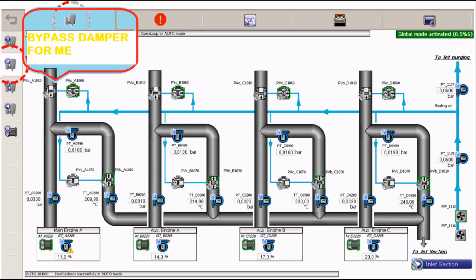The bypass damper goes to the open position if the scrubber stop button is pressed, or the emergency stop button is pushed, or the pneumatic or electrical supply to the bypass damper fails, or there is an alarm in the exhaust inlet module, or an alarm in another module or device that stops the whole scrubber. The damper control can be manually overridden with a hand wheel located on a crankcase.